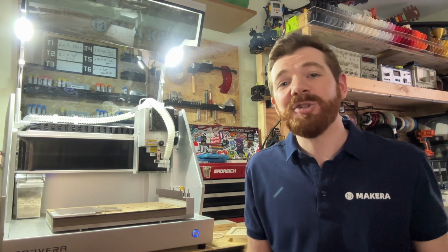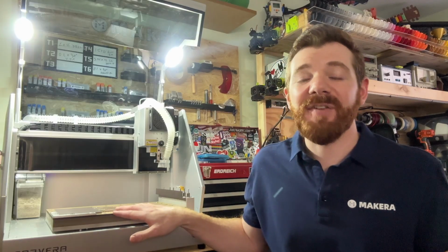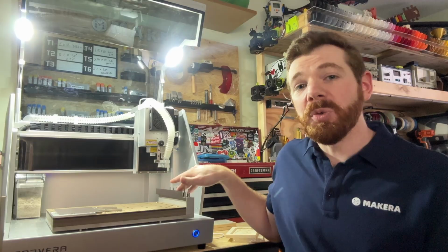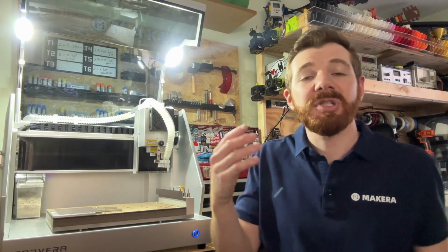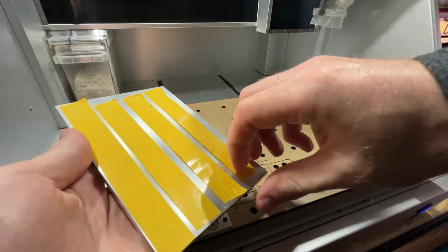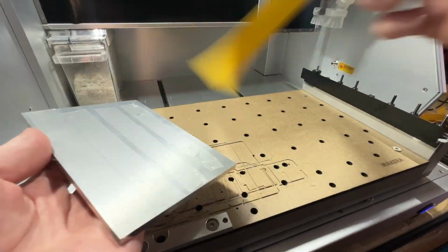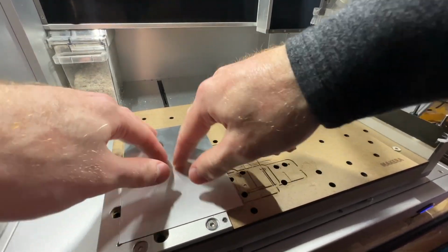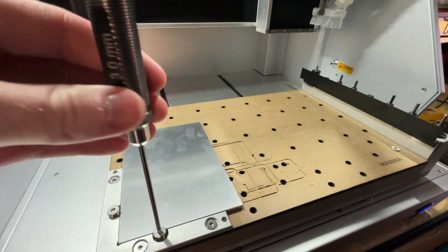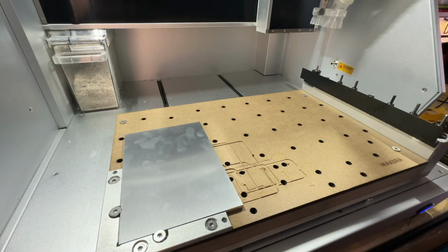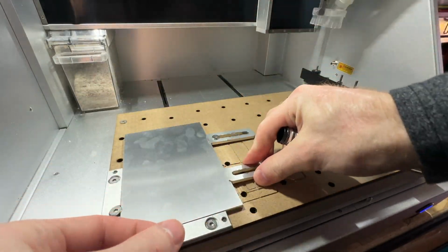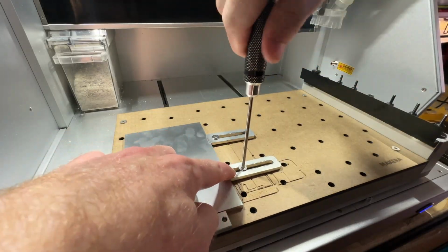With our GCode files created, it's time to actually set up our Carvera for manufacturing. The first thing that you want to do is check to make sure that your tools are located in the tool changer that corresponds with the tools that you have in your tool crib in SolidWorks CAM. Next, we can go ahead and secure the stock to the bed of our Carvera, and because we didn't use tabs, I'm going to use double-sided tape to hold down this aluminum stock. It is always a good idea to run this job using a softer test material like epoxy tooling board or polystyrene, as discussed in our selecting stock video.